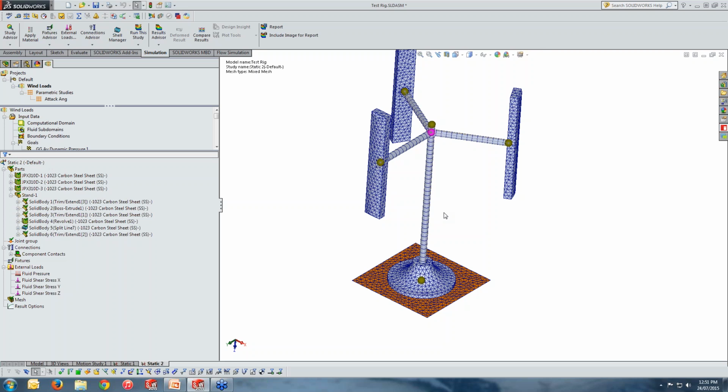Therefore, when you're having a solid attaching to a shell, you might create a hinge connection, since you might simply bond these two components with their translational degrees of freedom, but since the shell one or the beam one has 3 more to be bonded, they might create a hinge connection.